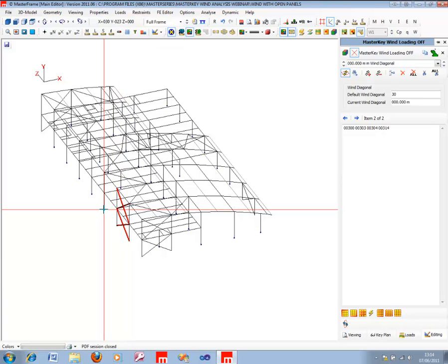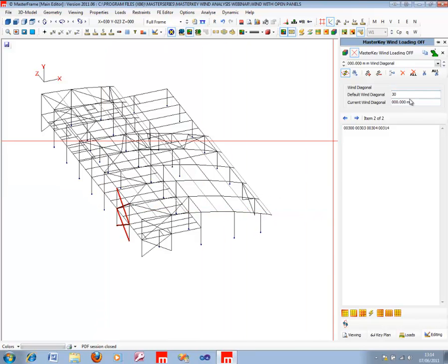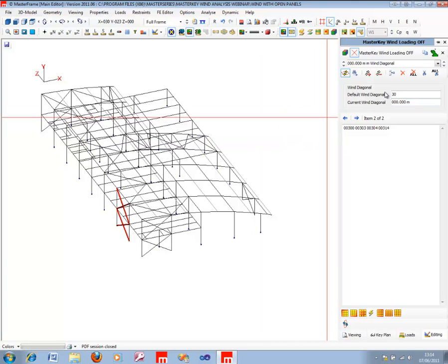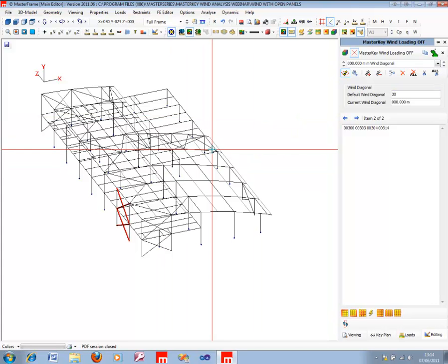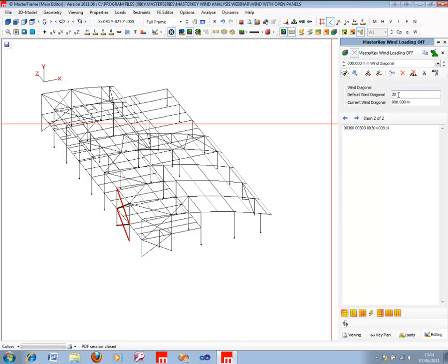However, we would advise that it's not always wise to set up the wind diagonals to say that you've got, let's say, another one of 35 and another one of 40 for lots of different members, because the downside is that for every wind diagonal that you tell the structure that it must consider, we get another whole set of wind loading cases that have to be analysed to cover that application of Q value. So you do get penalised on that score.